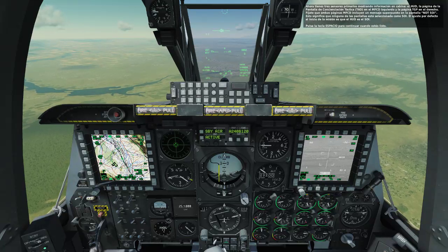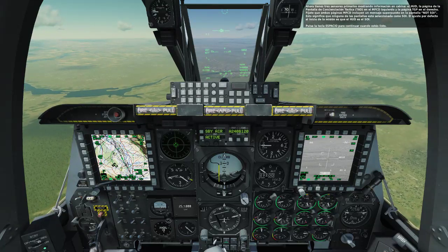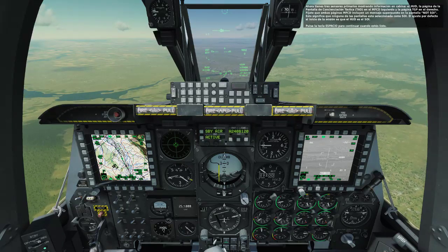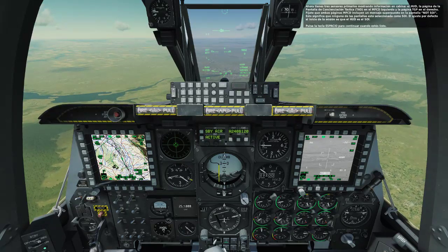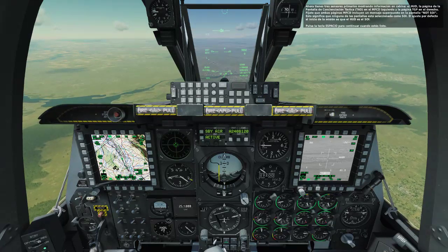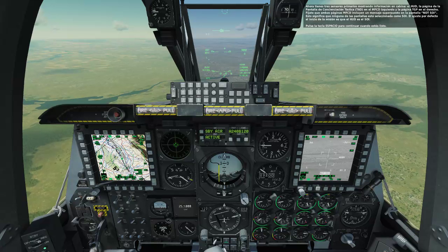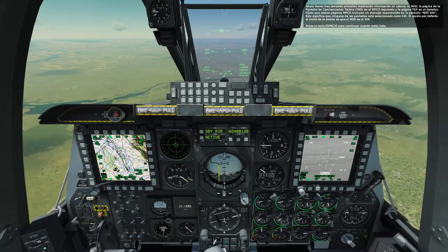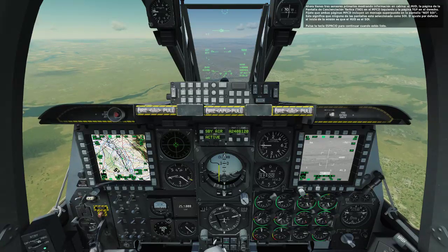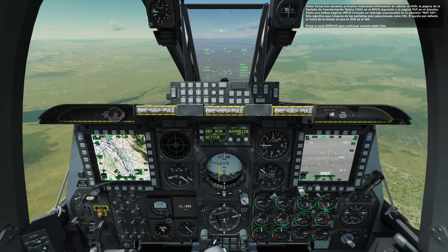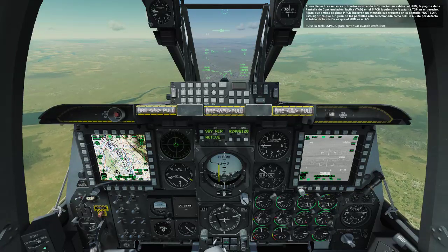You now have three primary sensors displaying information in the cockpit: the HUD, the Tactical Awareness Display TAD page on the left MFCD, and the TGP page on the right MFCD. Notice that both MFCD pages include a "not SOI" message overlaid on the screen. This means neither display is set as SOI. The default setting at mission start is for the HUD to be SOI. Press the spacebar key to proceed when ready.